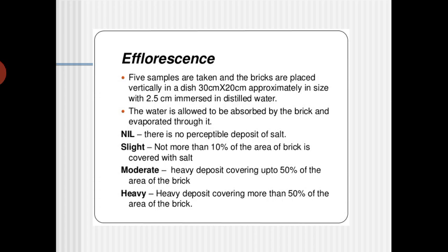But when you are doing the test for efflorescence, normally the conductivity of the water should be less than 15 microsiemens per centimeter. It should be completely pure distilled water. If you take completely pure distilled water and check its conductivity, it is less than 15 microsiemens per centimeter.